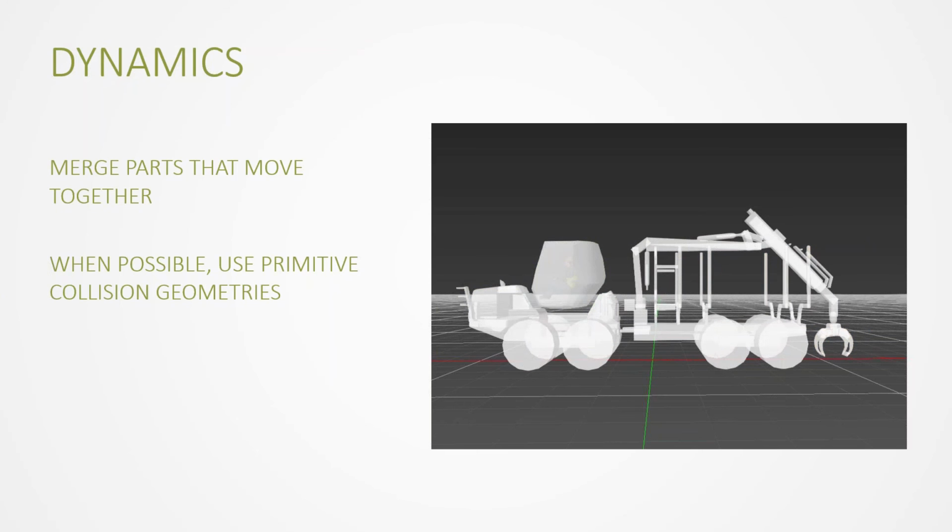And what we see here is the forwarder model from the Vortex sample. The rear deck is composed of arms that hold the logs together. Now, the entire rear deck is one graphical node, and a lazy designer, and I'm guilty of this when I first created the model, will just grab the node and attempt to use the automated tool to create one big convex mesh that's going to give it a collision geometry. But when you do that, and then you open up your part, you see that there are several hundreds of little parts that the computer attempted to fit to exactly match all the curves inside that graphic node.